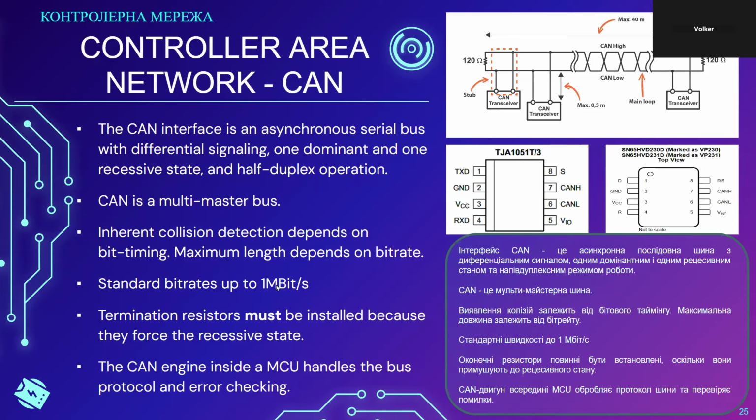Why would you do that? It's because of what I mentioned about the current consumption, because very often you want to separate the power domains. You want to separate the power that goes to the CAN controller from the power that goes to the microcontroller. If the microcontroller is using 3.3 volts, it sometimes uses these 3.3 volts as a reference voltage for its A to D converter.